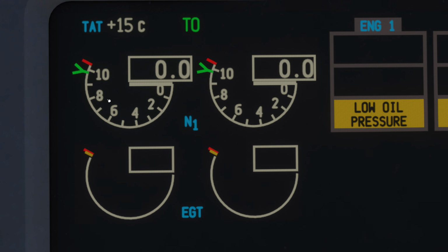While the engines are most efficient there, they also have the largest change in thrust percentage compared to the speed of the fan. Therefore, you can say that changing thrust between 60 to 100% has a much, much greater effect than changing it between 20 to 60%. So a thrust gauge eliminates that problem and tells you a direct relationship.